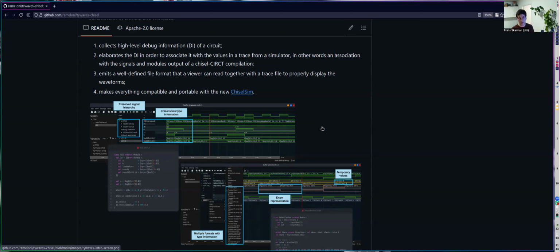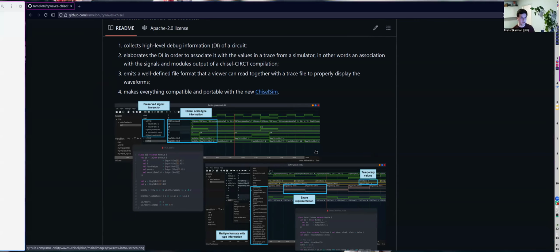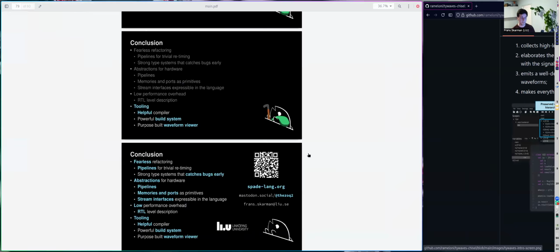Which at that point you kind of need ready-valid stuff. I have a broken thing in Spade pipelines now where you can put a condition on a register for that to accept new values, and that will kind of propagate up. The problem is I realized too late that if you do that and you have a sub pipeline, that sub pipeline also needs to know that the main pipeline is stalled.